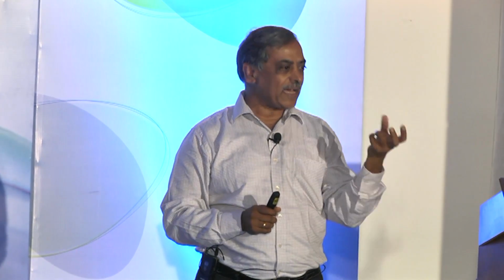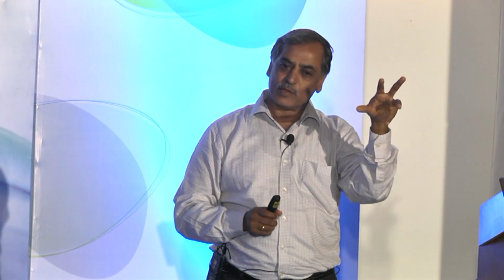In a quartz movement, in a quartz watch, similarly, you have an energy source, you have an oscillator, you have a converter, regulator, transmission, display. In the case of a quartz watch, the energy does not come from winding, it comes from a battery. There is a step motor and an electronic circuit board, ECB. They convert the oscillation into pulses. The pulse will make the wheels move, rotation happens, and thereafter dial and display and hands.